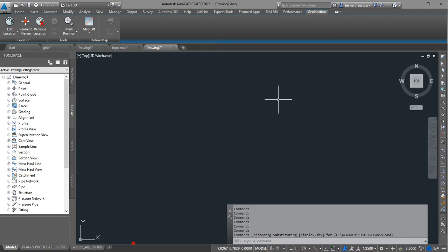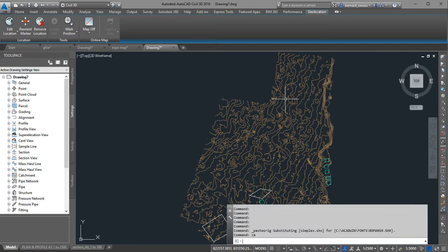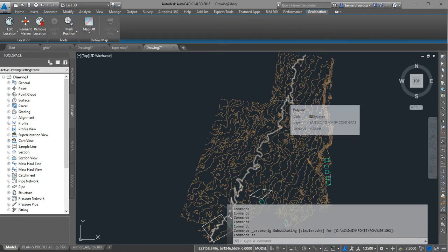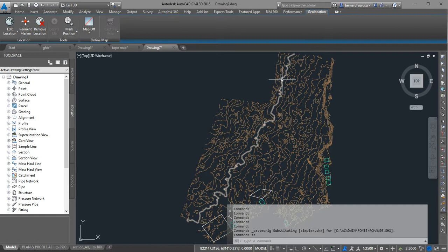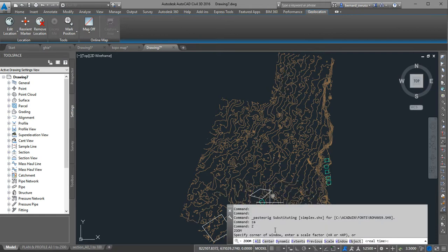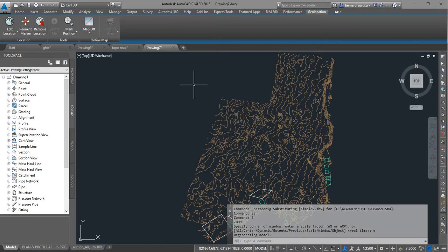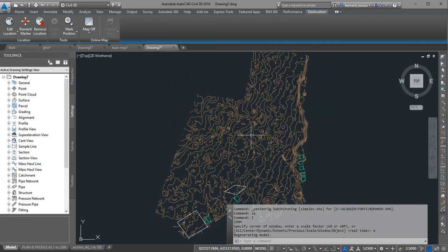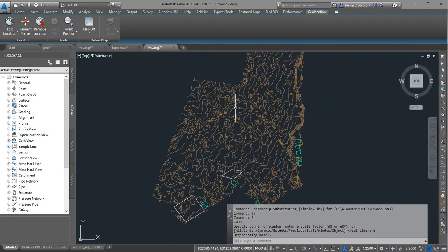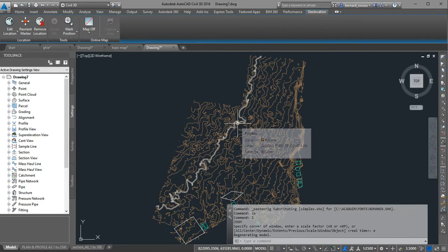But if you double click on your scroll or you type ZA, some computers or some versions, when you type Z, may tell you there is an unknown command. So you can use the scroll. If that does not work, you just type Z for zoom, then select E for extents, and it also will display everything. So this is what we have in our new drawing, which has the S&D template settings. Please, are we okay? Okay.